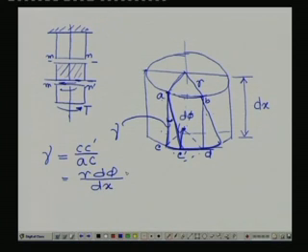Now, what is seen is the angle of twist, meaning with respect to this face, how much this face is rotating by virtue of applying this torsion T. Now, this particular d phi is proportional to dx. So, we can find that d phi by dx is a constant term.